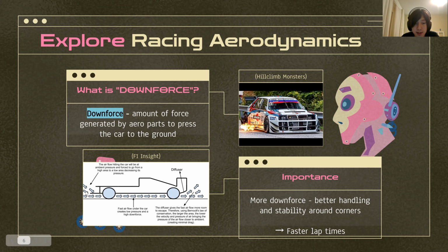When the air gets sucked in, it goes through the underbody, gets accelerated through the diffuser, and goes away from the car. Through this process, the airflow underneath the car is increasing in speed and therefore creating a low pressure zone below the car. Using this pressure difference from above and below the car, you press the car firmly to the ground.